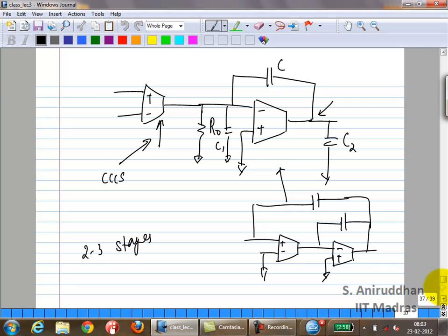And now we also said that, for example, this is an example of a two-stage op amp. Okay, so you have two transconductance stages. Now if you make the second stage into a more complex stage, like here below, you can get a three-stage op amp. But more than 3 stages is very, very uncommon, because now you have lots of nodes. Each node has a parasitic pole, so you'll have a problem with your phase margin.